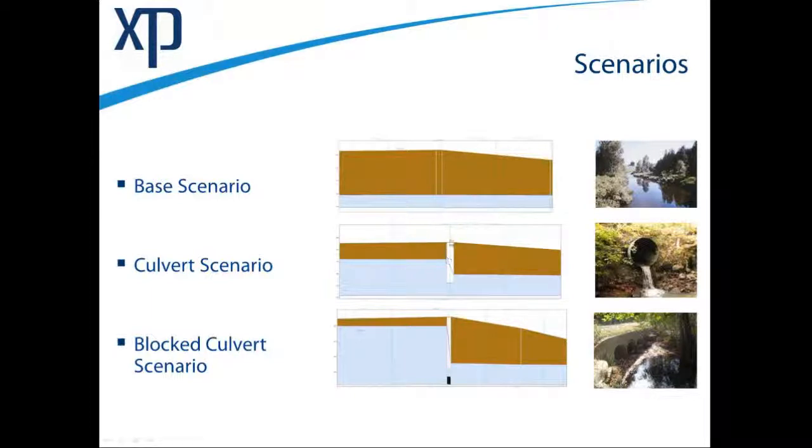The second scenario that Ludmila will run through is how to design a culvert to convey the flow that's occurring there right now satisfactorily. And that's the second shot down. So if you look at the culvert scenario, you can see that there's a sort of white zone here. This is telling me that there is depth of cover above the top of the culvert. So you'll see the sort of blue is the depth of the water within the natural watercourse, then flowing through a culvert and then through a watercourse on the downstream side to the right-hand side.